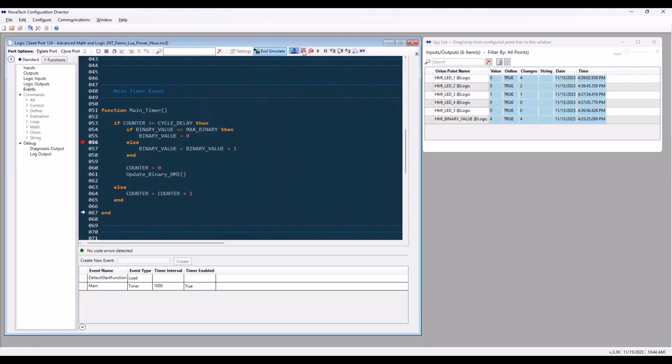So I believe if you toggle the breakpoint, there, I could set this. If I want to set a breakpoint down here, I can set another breakpoint. So these are just additional stopping points. I believe when you step out of the function, this will force the simulator to stop at those points. It gives you extra levels of granularity when you're looking for specific issues or problems you're having.